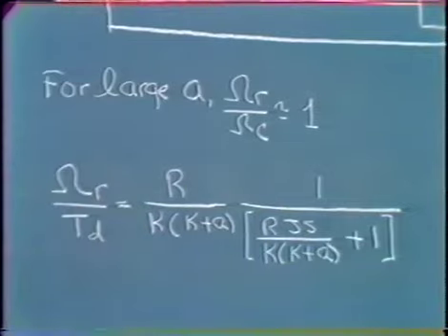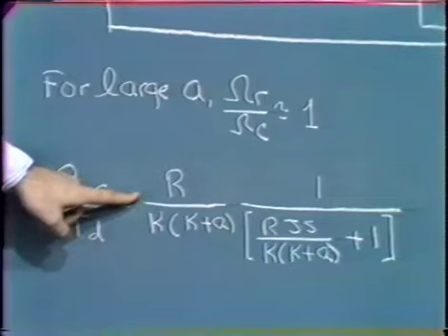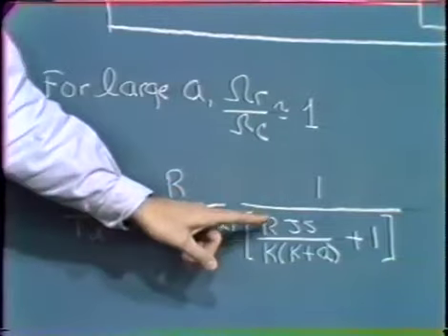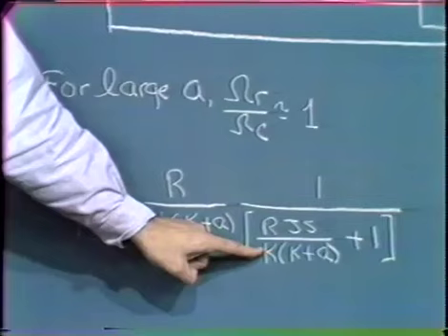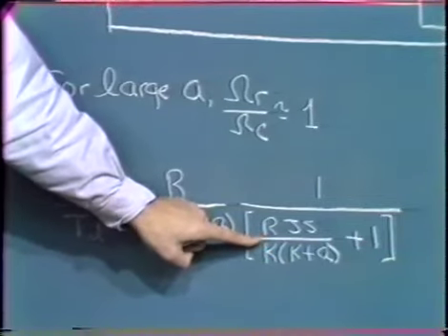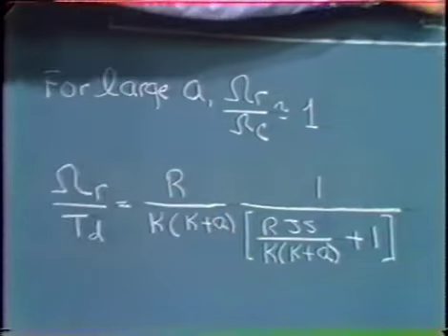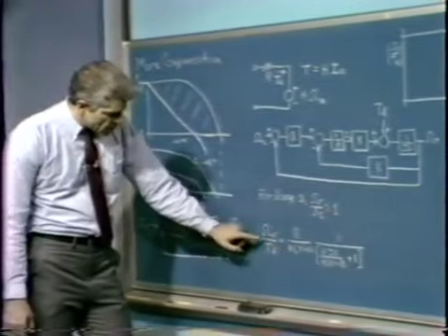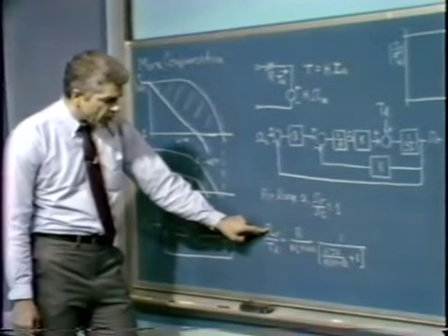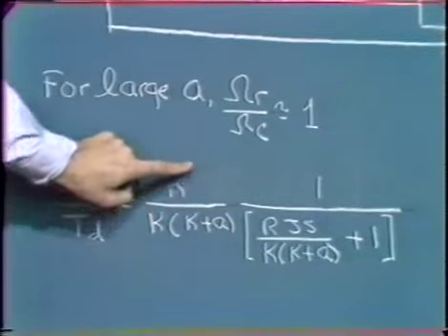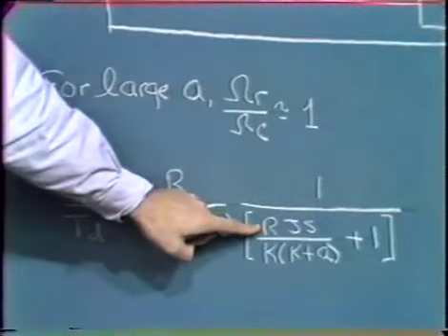So this collection of constants out in front gives us the rejection, if you will, at low frequencies. This is hopefully a small number. And then at some higher frequency, we get a single pole associated with this transfer function, reflecting the energy storage associated with the rotating inertia. So our disturbance to controlled variable transfer function has some low frequency magnitude given by this expression and then a single pole.